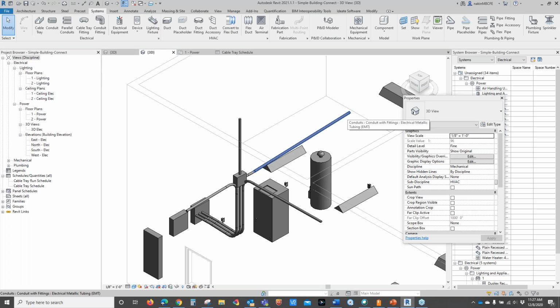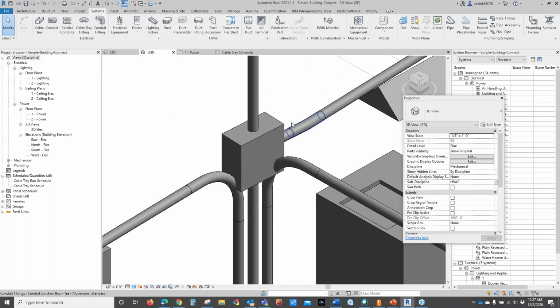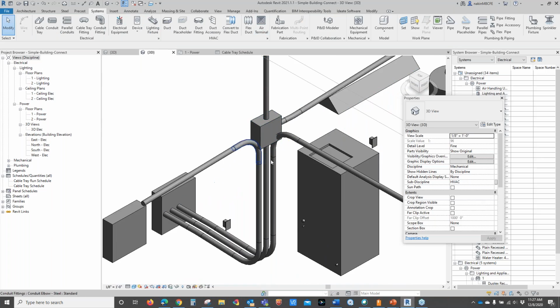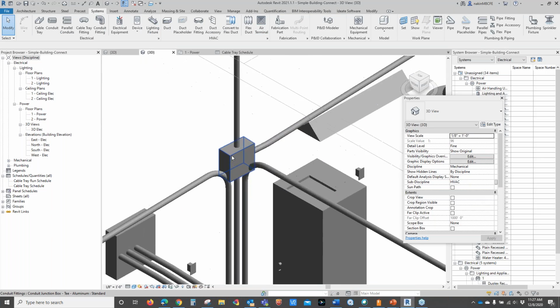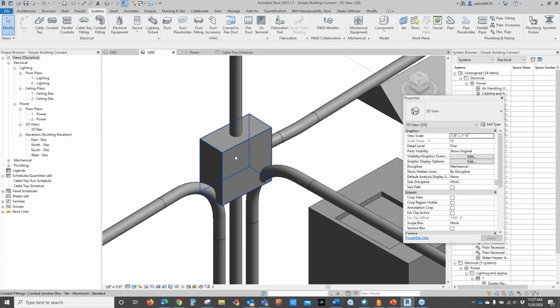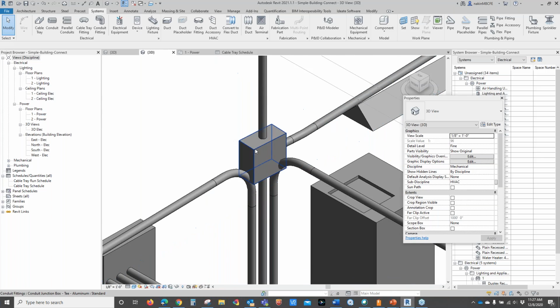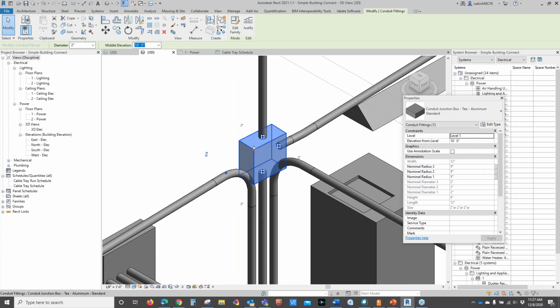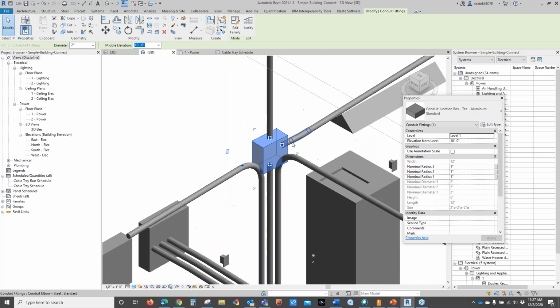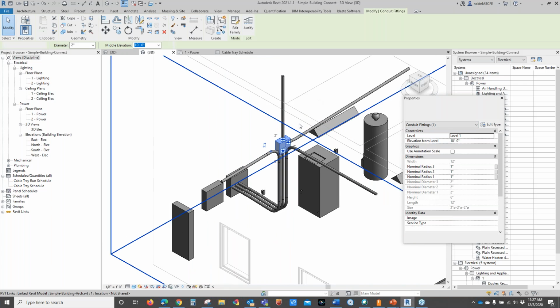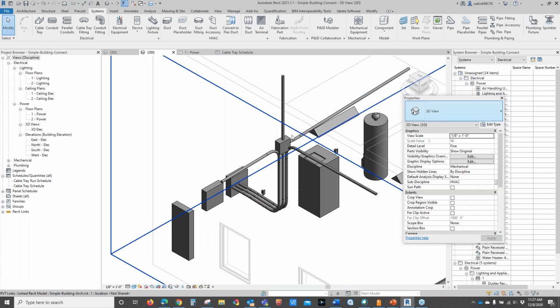Okay, and you see what happened with those conduits going up and out. It placed the junction box in this conduit. Of course, now I've got to come back and readjust all of this information to put that box in there. But the junction box will come in automatically when it's saying I've got too many branches here and I can't do that.